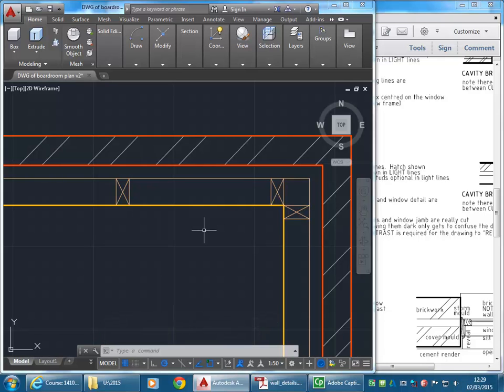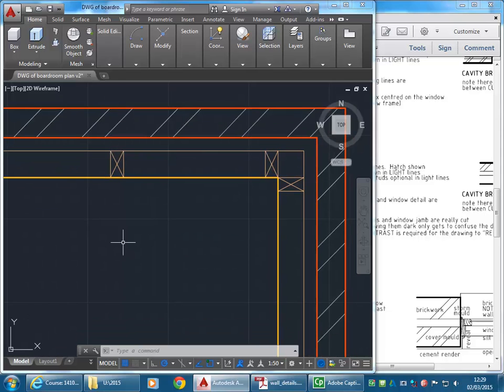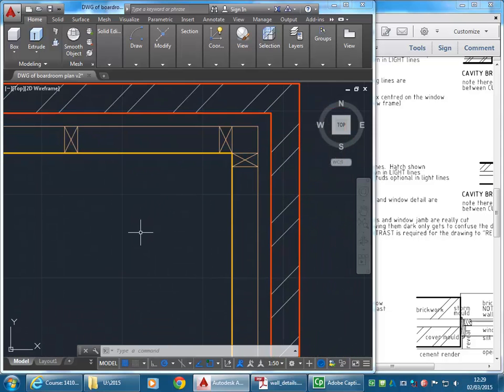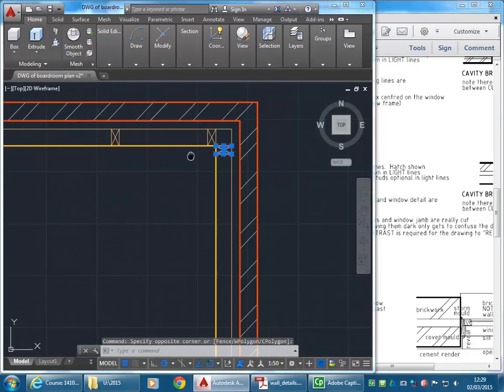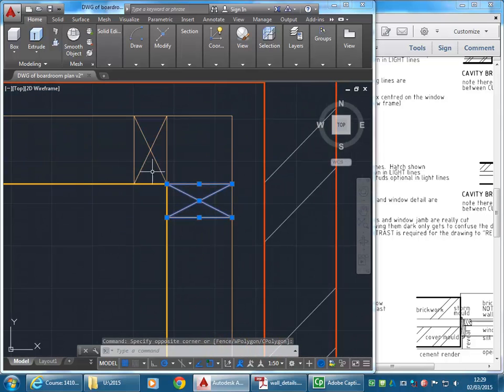Yeah, absolutely. Normally you can just use the standard spacings and work with that. But if you've got things that need to be supported from the wall structure, you have to add extra. You only show that in the detail, so they don't need to be shown in your main floor plan. And you don't need to work out all the studs in your structure, as long as you've got an idea how it all is connected. The main thing here is that we have a stud at the corners, so they've got something to nail the plasterboard to.